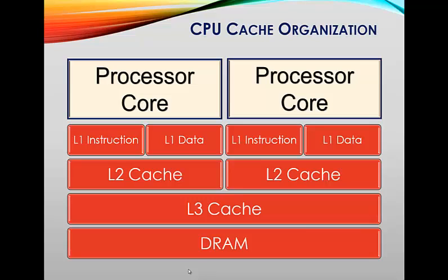If you were to look at a very simple program with essentially a single instruction, and you were to fetch that instruction and run it, it would be fetched from your memory into level 3 cache, then into level 2 and level 1 cache, the L1 instruction and data cache, and then go into your core processor and get processed.